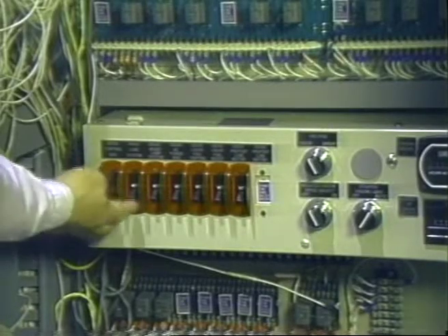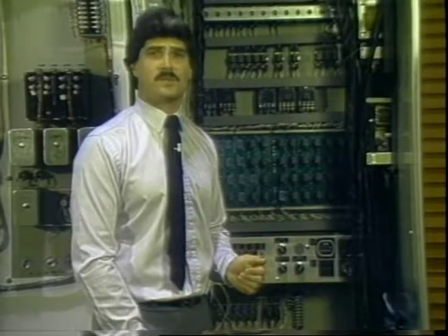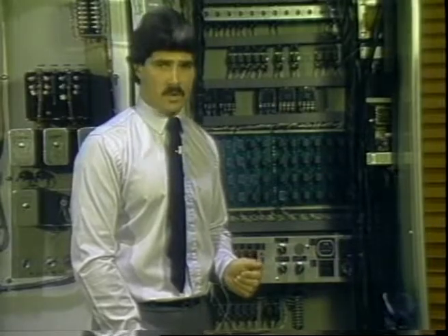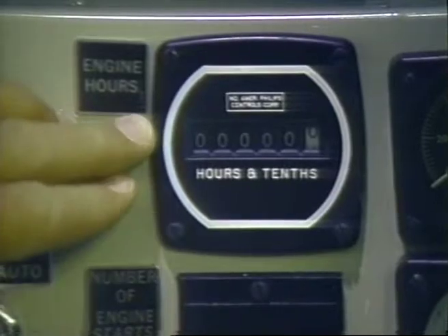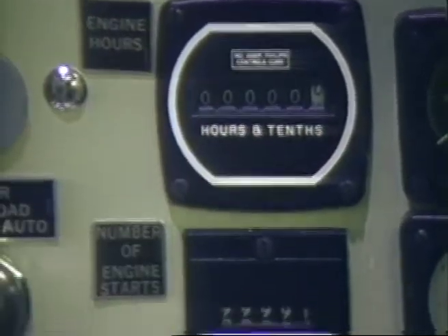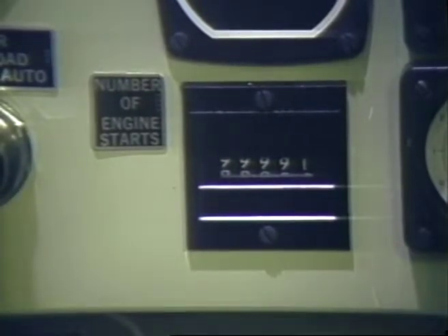Also installed on the circuit breaker panel are the DC system branch circuit breaker switches. These switches are turned to the on position prior to positioning the system control switch to auto, remote, or local. When the engine reaches 60% speed, the hour meter begins to record the number of hours of engine operation. The start counter counts the actual engine light-off starts.